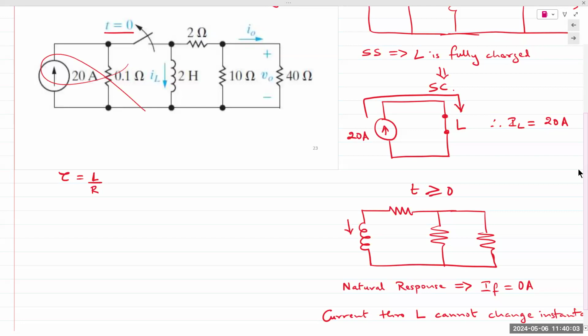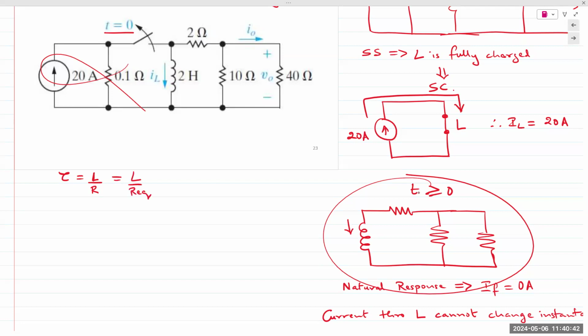The equivalent resistance, the answer is absolutely correct. We are analyzing only this circuit. So the stored energy in the inductor is being delivered to all the resistors that are connected to the inductor. The resistors connected to the inductor are the 3 resistors on the right, as shown in the circuit diagram. All of them receive that inductor energy. So we have to find the total equivalent resistance, Req, as seen by the inductor.